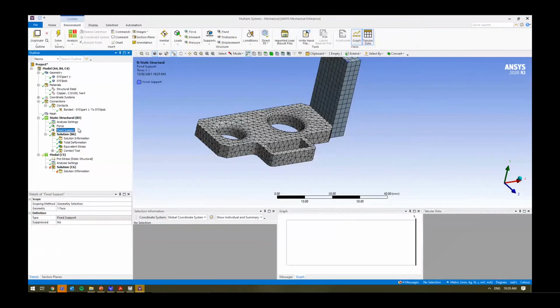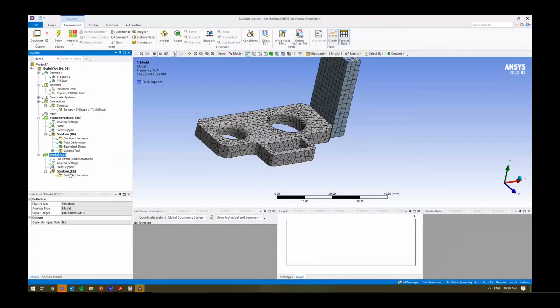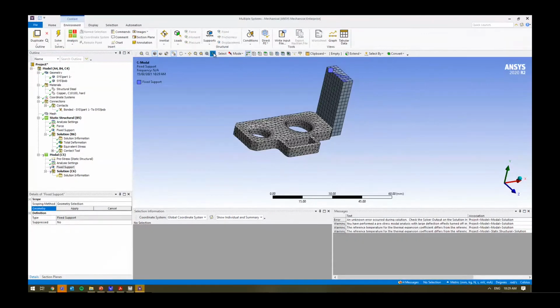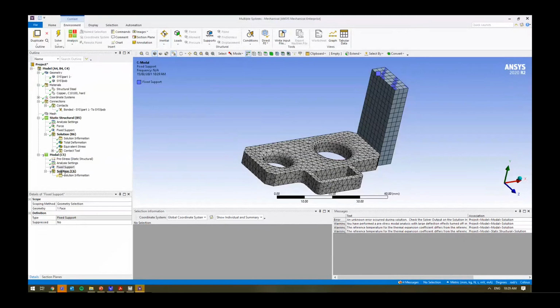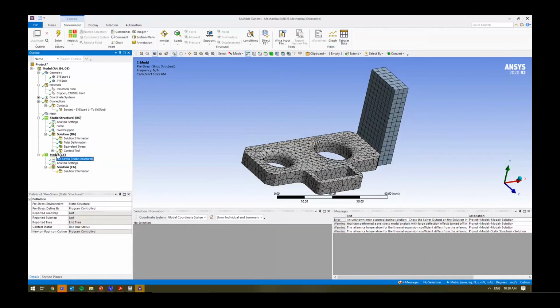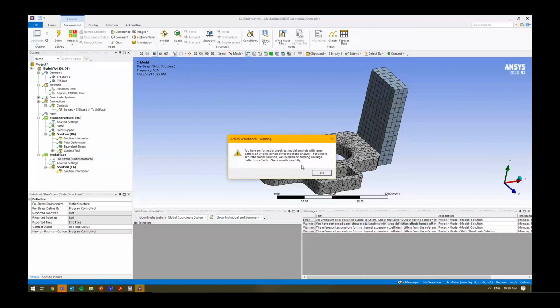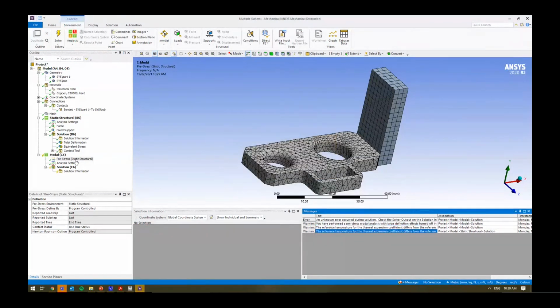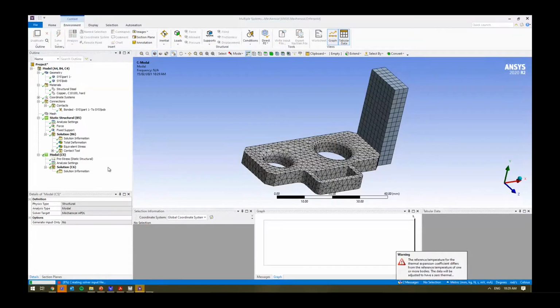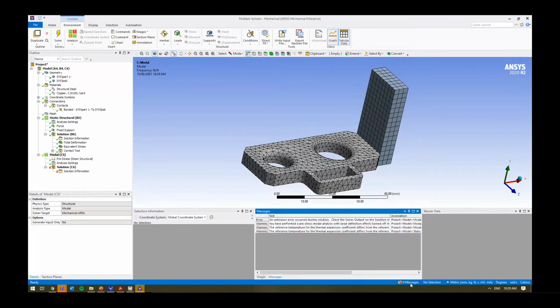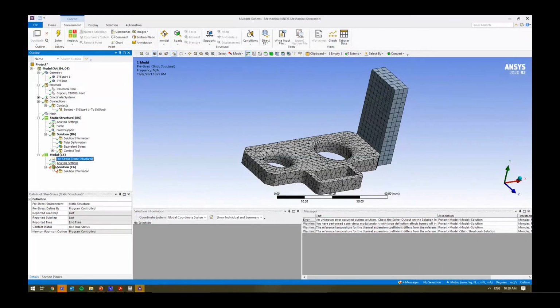All right, so what do I have here? I don't have any boundary conditions. Let's bring this boundary condition over up to that face there. Hang on. So what do we have happening here? So let's have a look at the errors. You don't need large deflections, and that should be fine. Cool. So that's happening. We'll get rid of the pre-stressed environment for now.